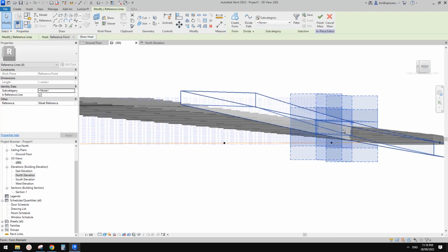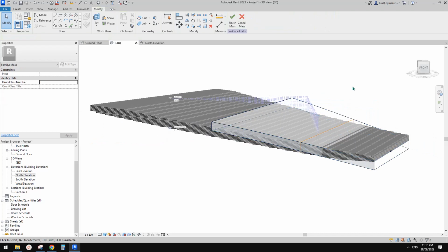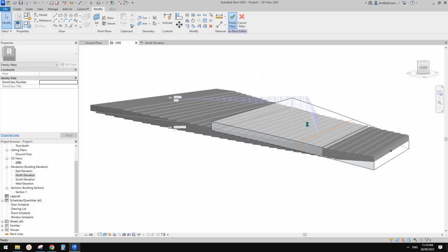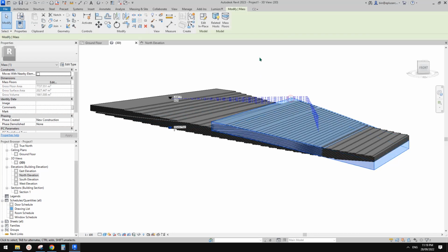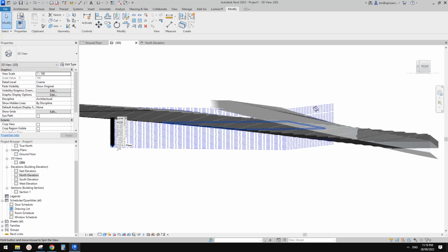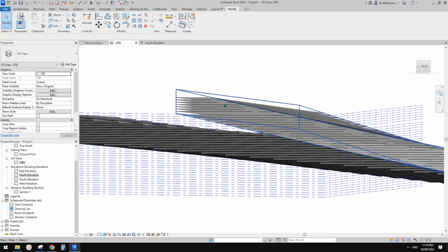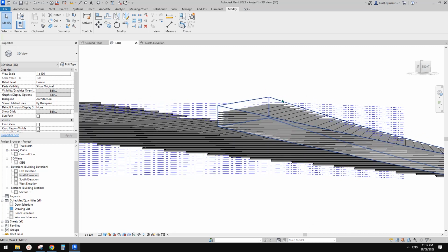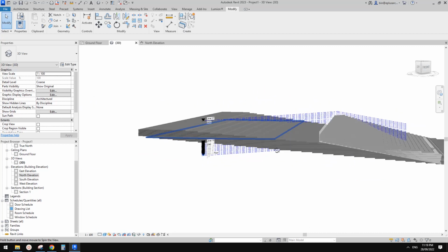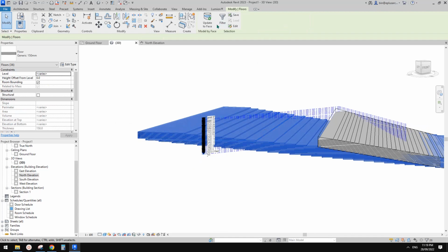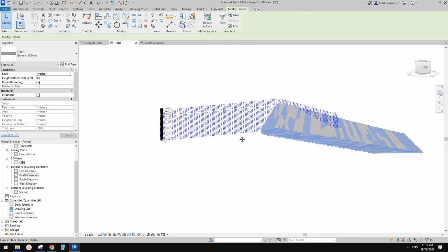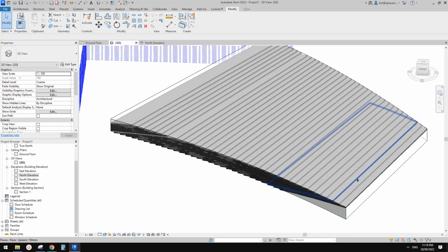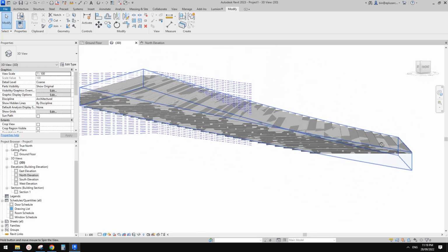Use a keyboard. Okay, so let's see. Now finish this mass, and once again select this mass, and I think the mass floor will automatically adjust to match this mass, but these floors won't. So we need to select all and then use update to face. So now you'll see we have less. So the depths of these treads become smaller.